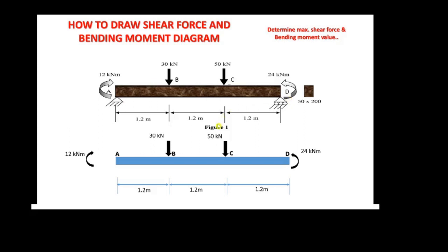Okay. The corresponding forces for the pin support look like this. We have one vertical force and another one is a horizontal force. The value for horizontal force is 0 because it is the only horizontal force acting on the beam. Remember, all the vertical and horizontal directions should cancel each other out to remain in equilibrium. The corresponding force for a roller support looks like this. Just one vertical force.